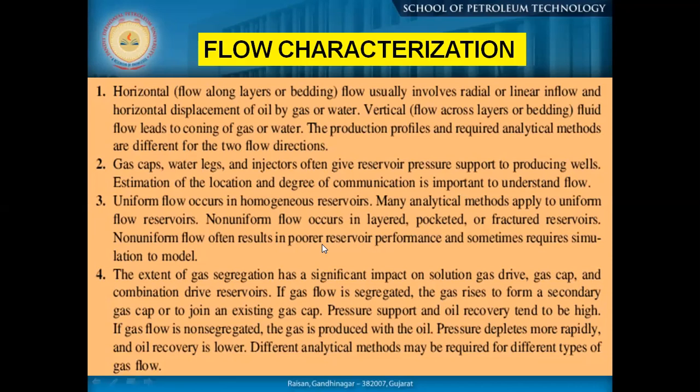We discussed this part earlier. When gas is coming and you allow it to flow, you are actually losing the energy of the system. So what happens if gas is coming and you have a top perforation? You close the perforation so that the gas is stored on the top, and as gas is highly compressible in nature, it will help us with the driving energy. So this is how, with time, you may have to work for your optimum reservoir production.